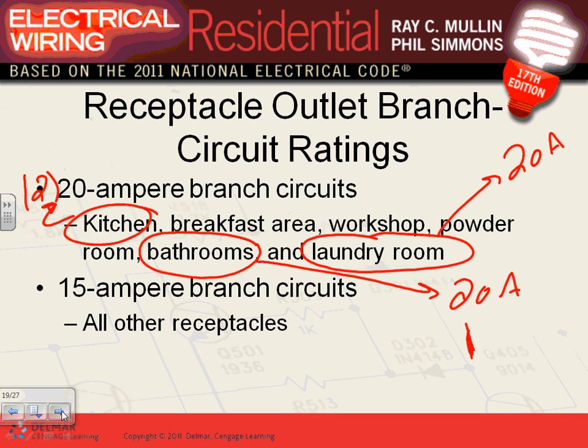You know how you just mentioned the outside GFCI receptacles? Where does the code talk about whether you can move from inside to outside? Yes, as long as you don't tap from a kitchen circuit, a bathroom circuit, or a laundry circuit. See the point? By the way, Phil and Rob, you see these three places? I call them sacred cows. On these circuits, you cannot tie anything or feed anything out of these places. The only other area allowed to be fed from the kitchen circuit is the dining room. That's all, dining room and kitchen.